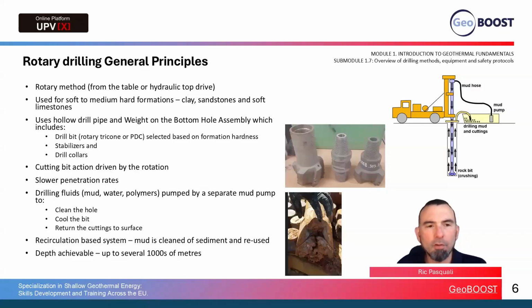The second method we want to cover, which is really quite common and used in many different types of subsurface conditions, is the rotary drilling method. So the rotary drilling method is basically driven by the rotation of a drill string. And you can see in the diagram, the drill string is the purple section going down to the bottom, and that rotation is achieved by a hydraulic top drive.